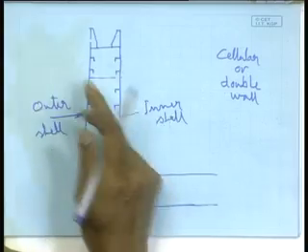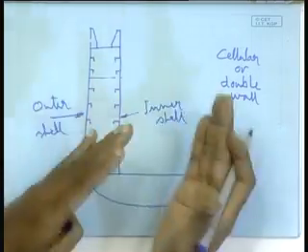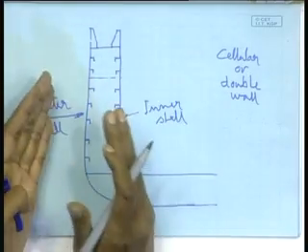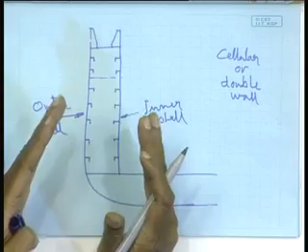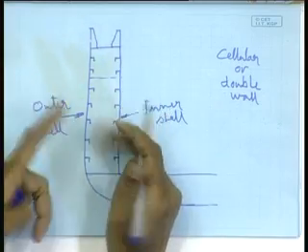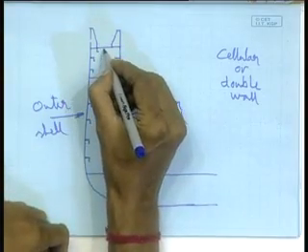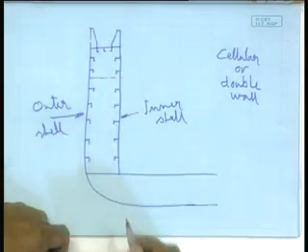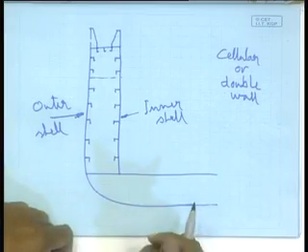So, both the shells, the inner shell and the outer shell, or both the walls, are longitudinally stiffened, as well as obviously the deck is also longitudinally stiffened. The whole thing is longitudinally stiffened. And then, as in this case, you had the transverses, right.